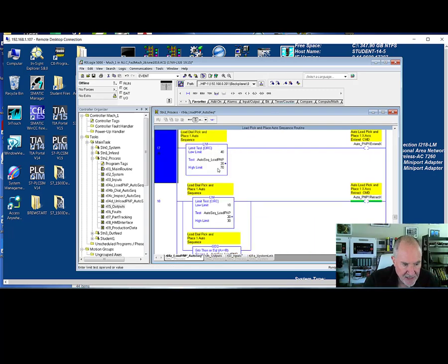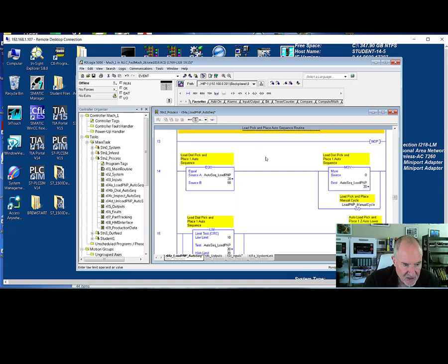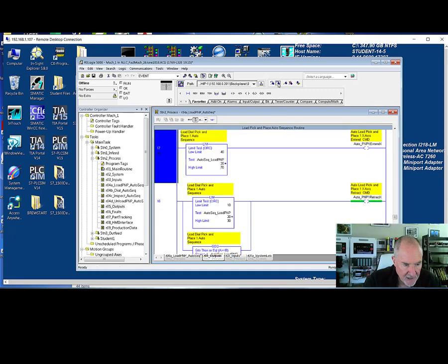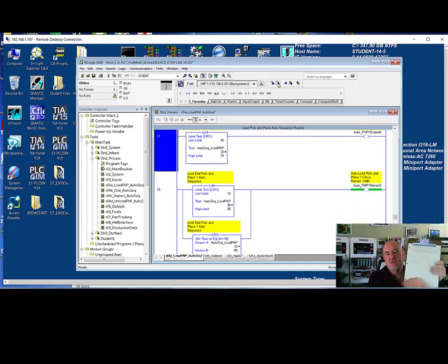And I can find that I should be between steps 40 and 70, so this is not on. So what stopped me from getting to 40, I happen to know I can just scroll up, but I could also go through these bookmarks, and I will get back to it. Or I can use a sheet of paper like this and just list things out and then go from step to step. So if you don't have bookmarks, your next best bet is to write things down and just follow the bits, usually starting from an output bit and then looking at the conditions of the machines.